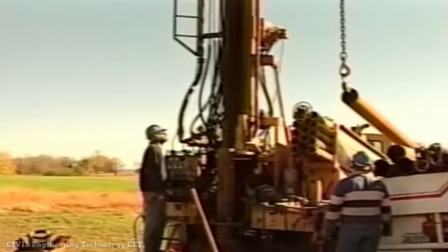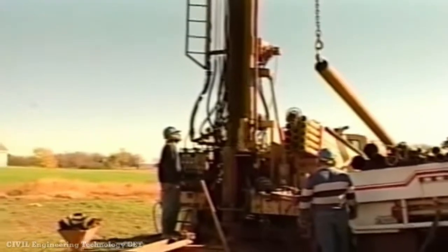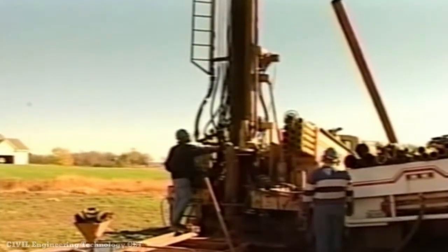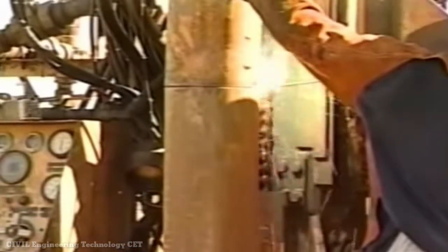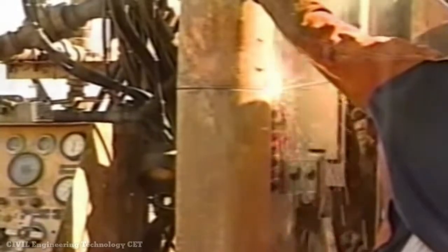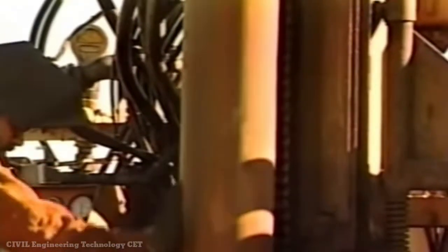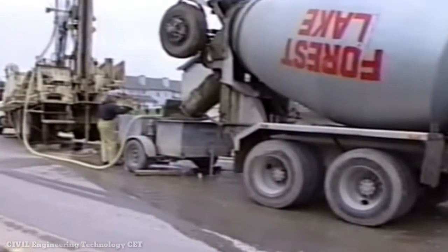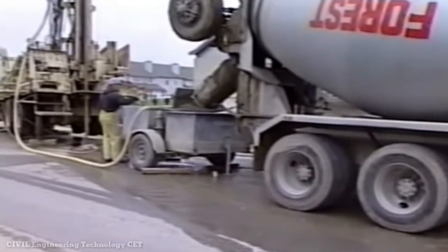No matter which method of drilling is used, the hole is usually lined with steel or plastic pipe called well casing. The type of casing used is determined by local geological conditions and the chemical quality of the groundwater. In most states, there are recommended well construction standards. The diameter of the drilled hole is usually an inch or two wider than the diameter of the casing.